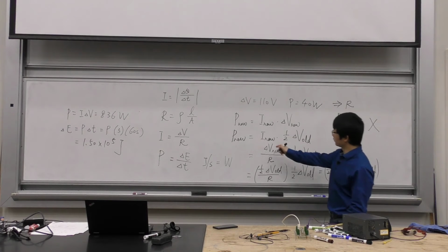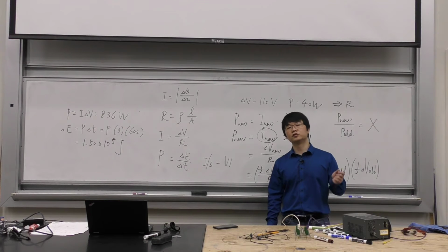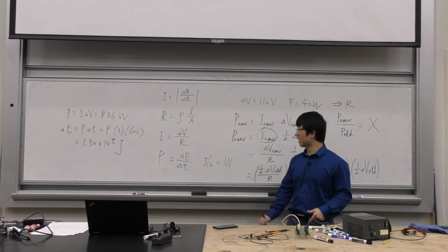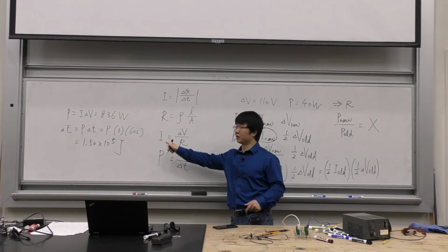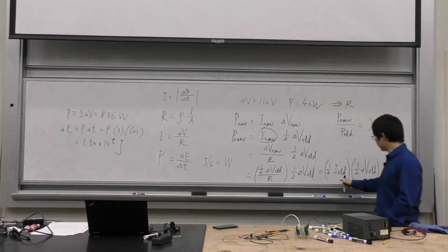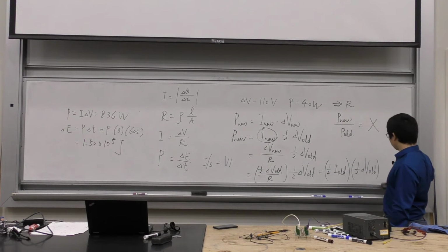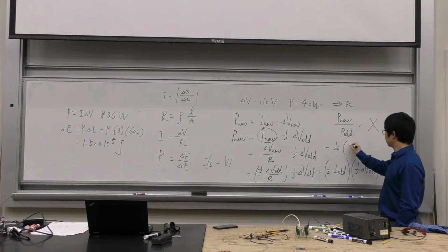Okay? So think about it, right? The new current: you connect this light bulb to a new voltage. The resistance doesn't change. The voltage becomes half. Take a look at this equation. Of course, this is going to become half, right? Because this number doesn't change, the voltage becomes half. So the new current is going to be equal to 1/2 the old current. Now if you factor out these two numbers, you get 1/4 the old current times the old voltage.